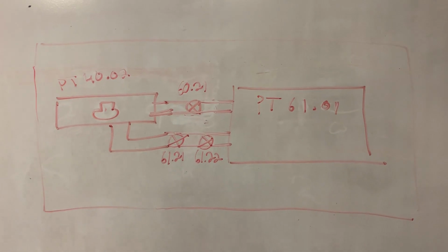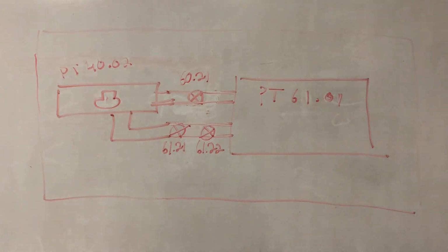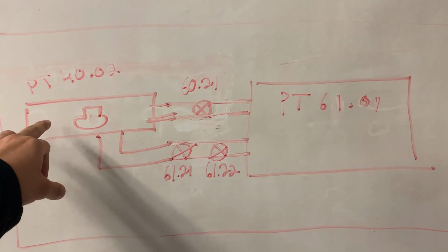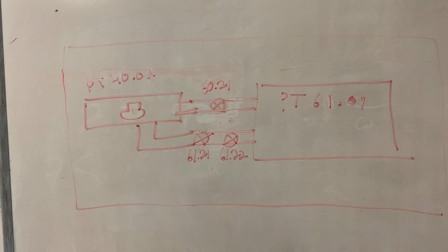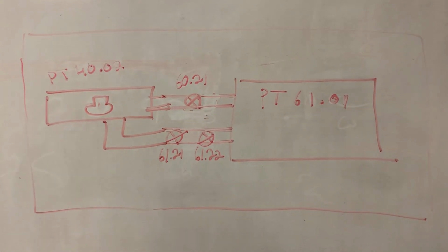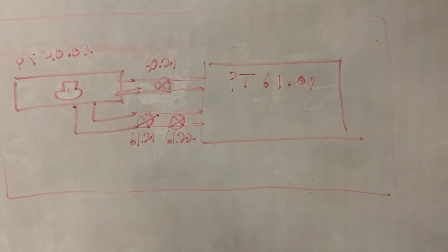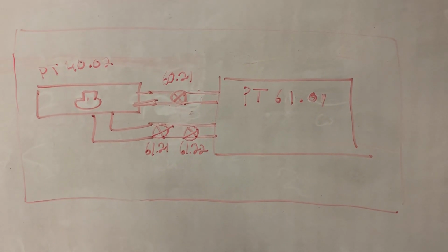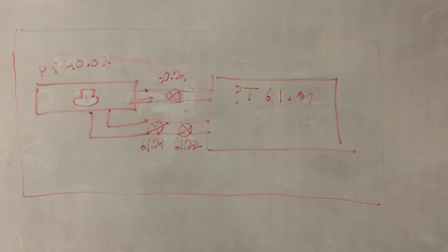In order to facilitate this, we have written a MATLAB script that essentially estimates the volume of the dewar and then takes the data output from our cryo system monitoring VI and tells you what the cooling power is. But in order to get the cooling power, you need to essentially run the cryo system until you're at a high enough pressure that you can have the cryogenerators pumped down over a sufficient pressure range so you have an idea of what the cooling power is, right?